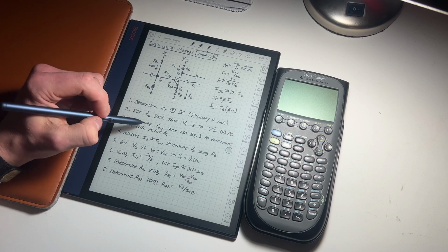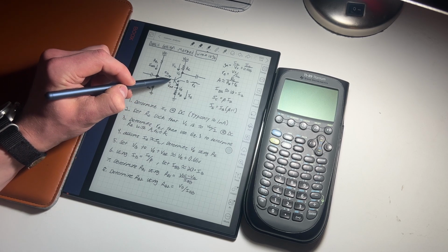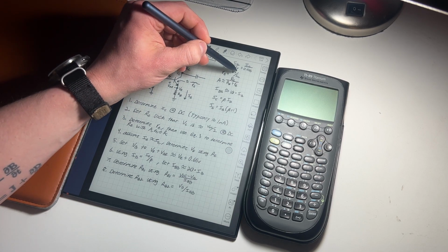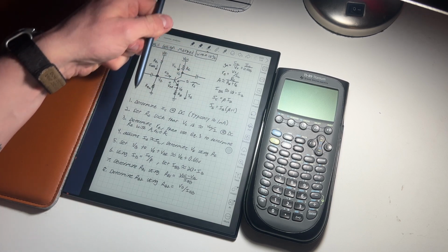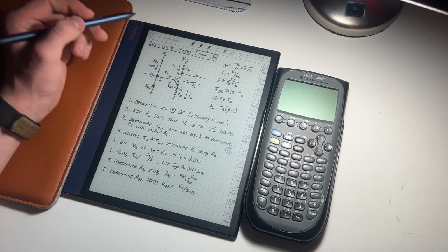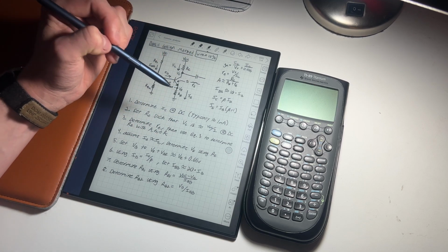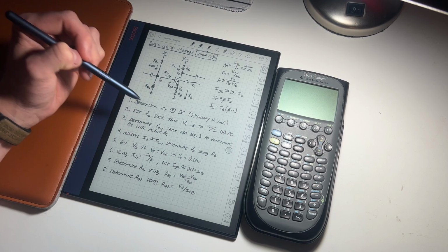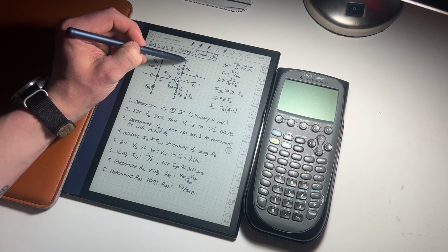Next, you determine little r sub e, which is the resistor approximation we used for the base emitter diode junction, using Vt over IC, and IC is your DC operating current through the collector. Then you use equation 3, the gain equation, to determine Re with the gain that you want, little r sub e, and the collector resistor that you set right here.